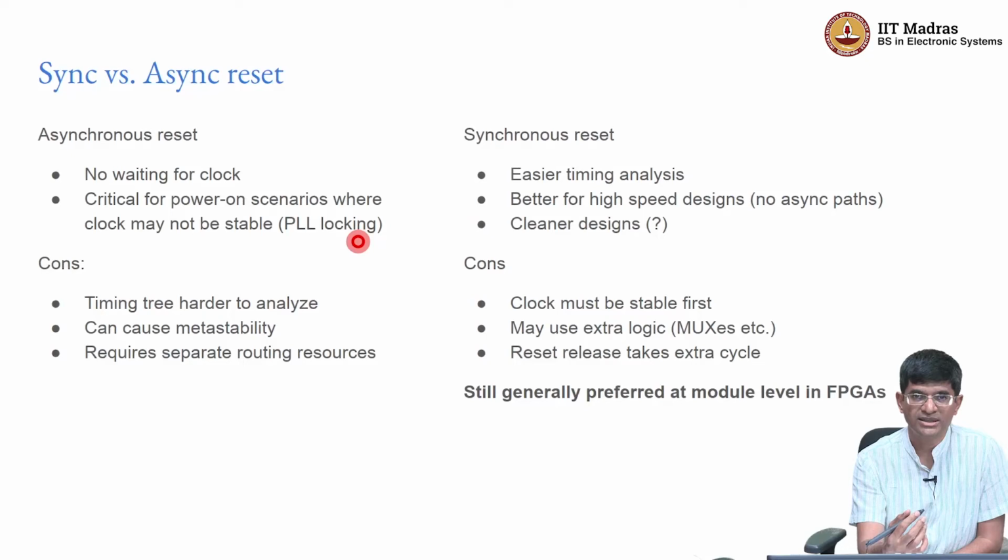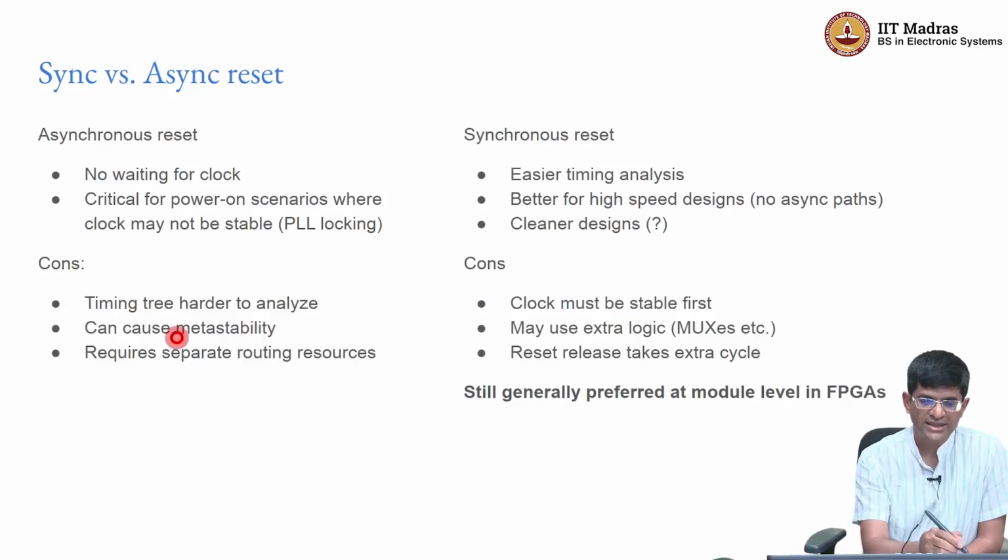The worst case scenario is, let's say you are trying to control the motor of a car, and because you did not reset it properly, when you just switched on the car, the first thing that happened was that it turned on the engine at full speed and made it crash into a wall, right? So you always want to make sure that your electronics has first stabilized before it has a chance of actually interacting with the outside world. In such a scenario, asynchronous reset is crucial. The problem with asynchronous reset is essentially related to timing analysis. That's one of the biggest problems.